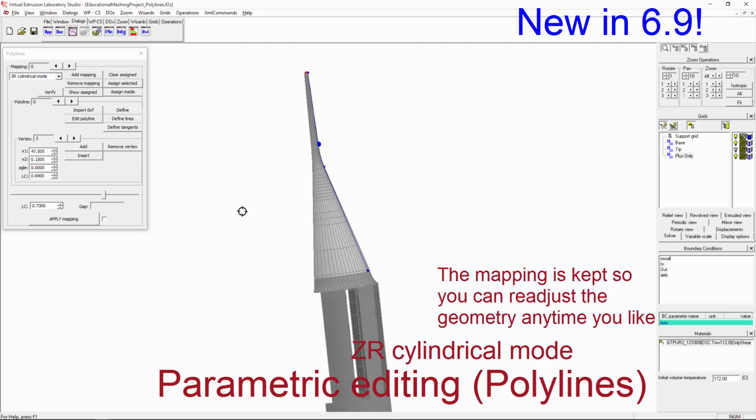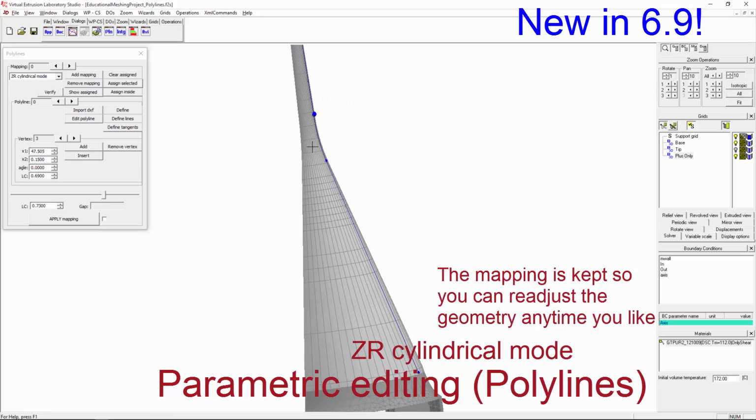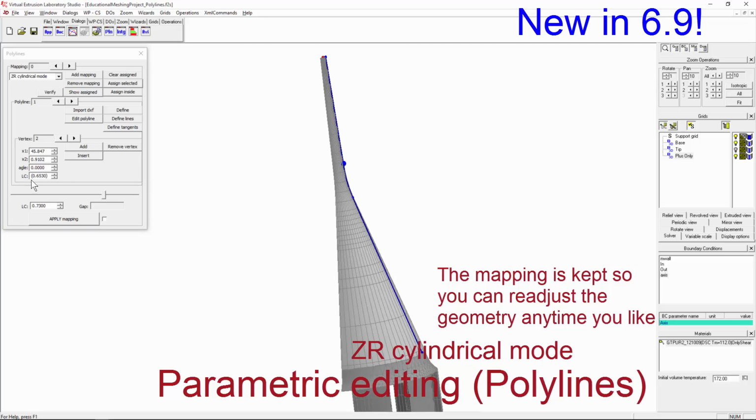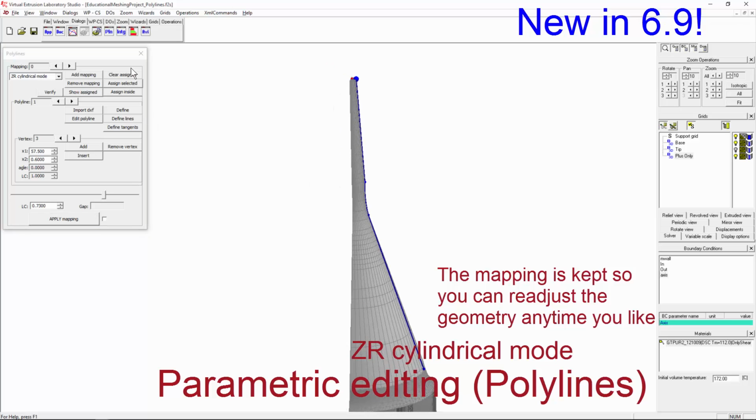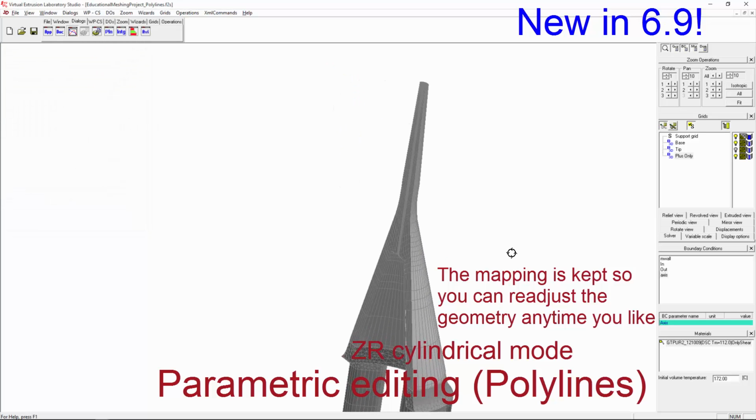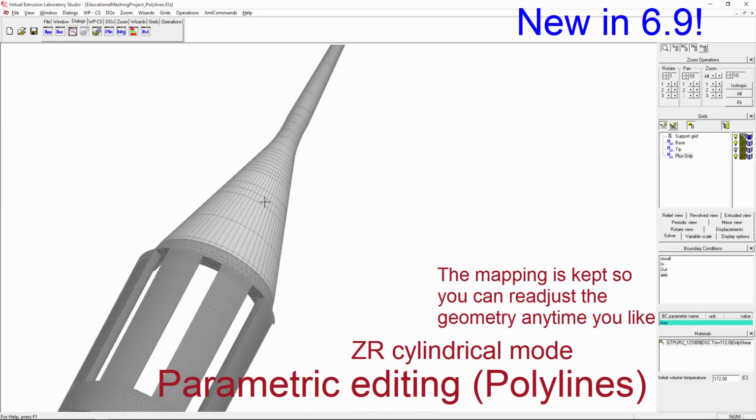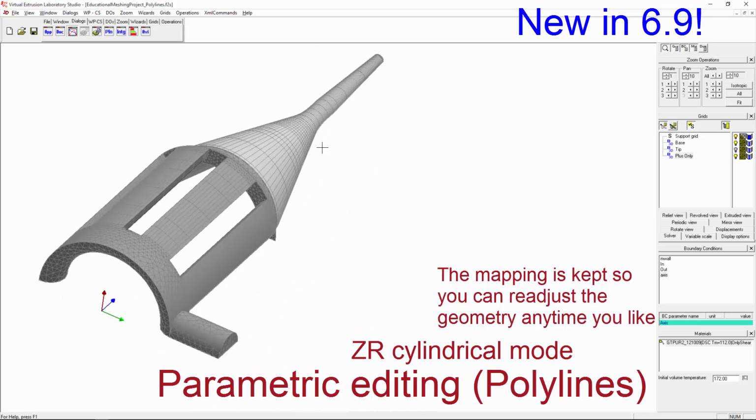You can change the radius, you can change the parameters. So the only thing you need to do really here is to, let's say, open that, well, I don't know, 1.2, and then also for the last one, you may do this to, let's say, 0.6. Okay, and when you say apply mapping, you just deform the shape to match those dimensions. Okay, and then you can resolve and see if there is any effect. So it's very simple to have a parametric entry.